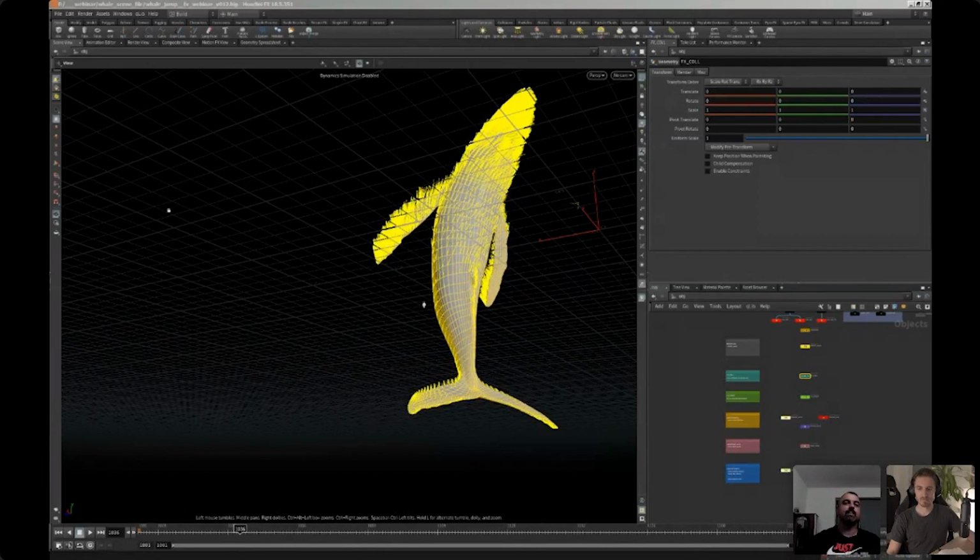Back then that was good if you needed to have hundreds of millions of points in a simulation. So you take a seed value, change it per simulation, so maybe 20 different seeds, and the wedge drop will save 20 different caches with the different seeds. When you load them back, you have in-between points, like for the same motion, with the wind and whatnot. So you get a crazy high-res sim.